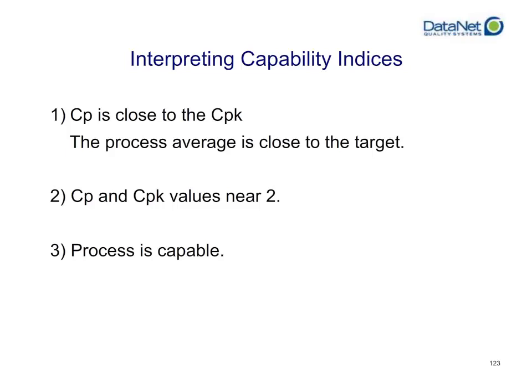Okay, now that we have calculated CP and CPK, what does this mean? The CP value is 1.94, which is pretty good by most objective standards. Now, I have no historical context. I don't know if this is better or worse than you used to be doing, nor do I know how your competitors are doing. But at least I know that objectively, most industry experts would say you're doing pretty well on your capability, your CP.